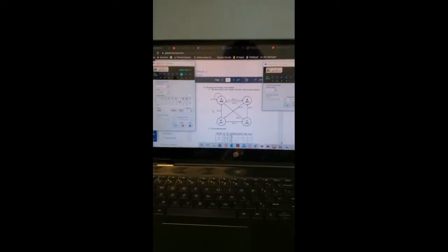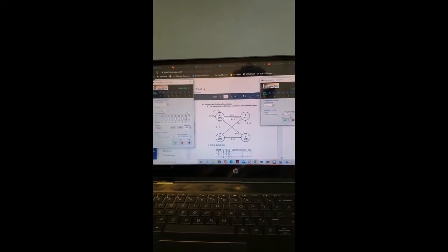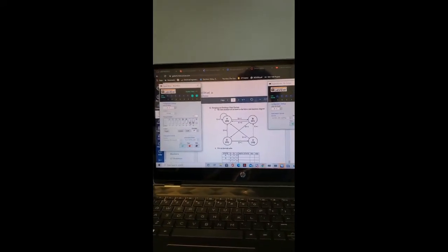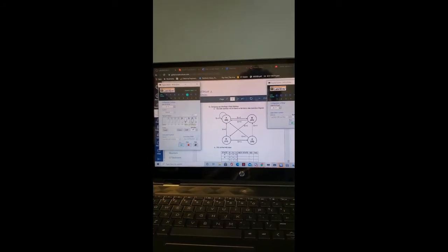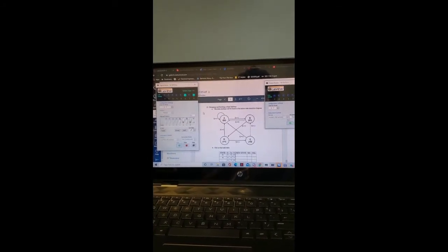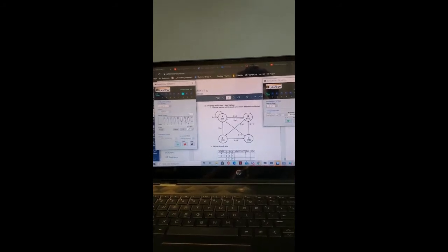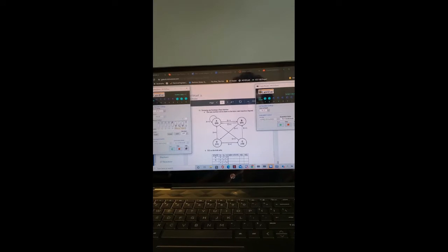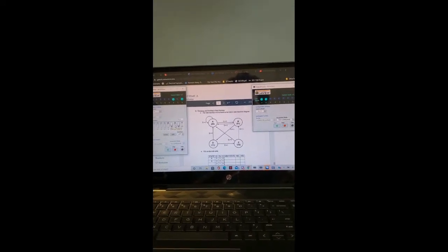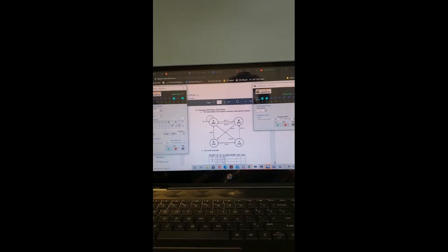And going through the truth table, anything with clear bar set to 0 doesn't work, so it has to be set to 1. But to go through the states, I start at state A, and with an input of 0, stays at state A. Input of 1 goes to state B, and then an input of 1 again goes to state D. Input of 1 again goes to state C. And then it cycles through those for all inputs of 1.